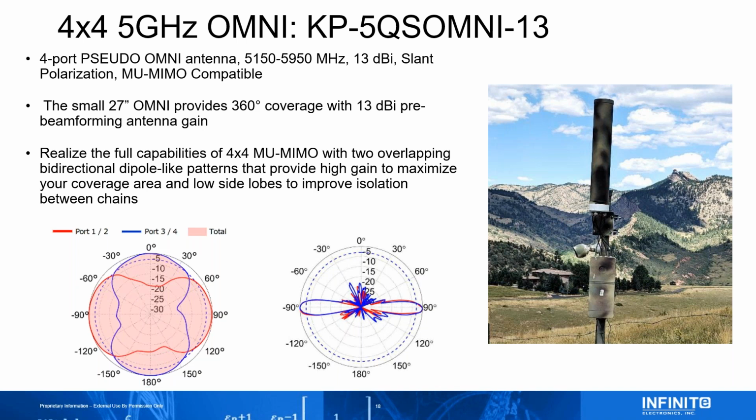So you want to make sure you're using that ePMP 3000 radio, but you don't want to really justify putting up 4 radios because you want to get this omnidirectional pattern because you have all the clients scattered everywhere and you can only mount the antenna right in the middle. So that's the kind of ideal scenario where you use this MU-MIMO Omni antenna with the ePMP 3000.